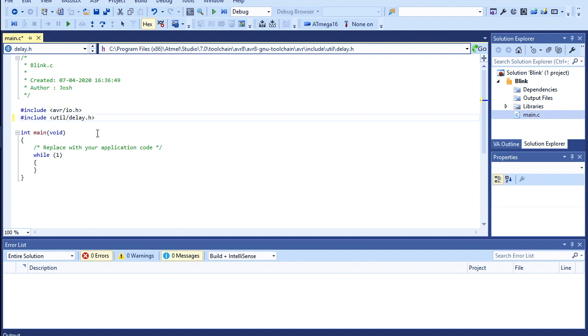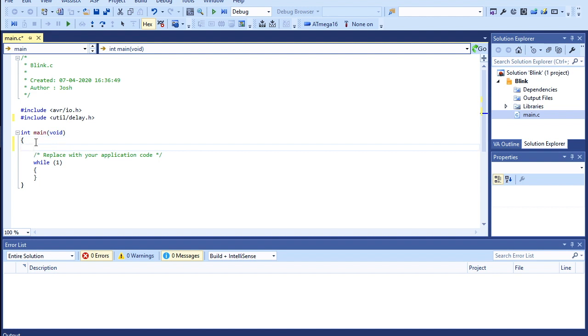So in our program, first thing as we discussed, we are going to use port C pin number 0. If we want to make it an output pin, we have to configure it in the data direction register, DDR, of port C. So DDRC is the data direction register for port C. If a bit is 0, then it is an input pin. If that particular bit is 1, then it is an output pin.